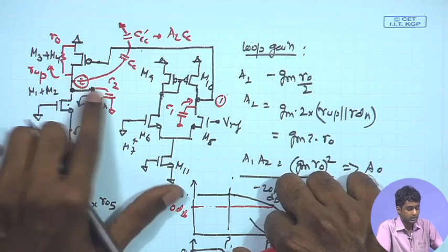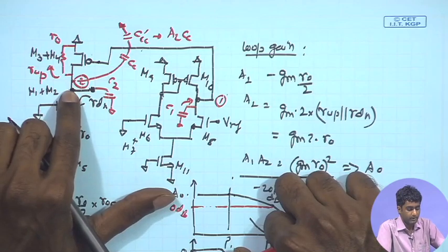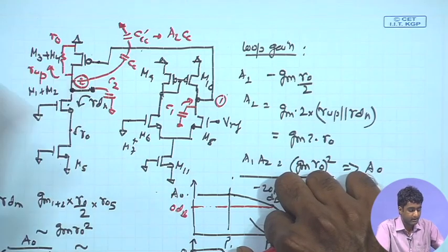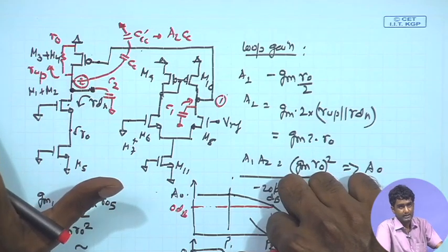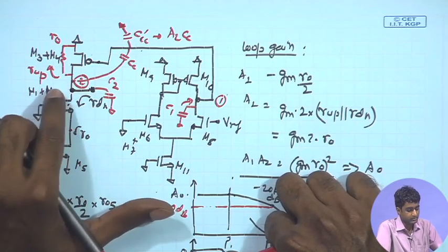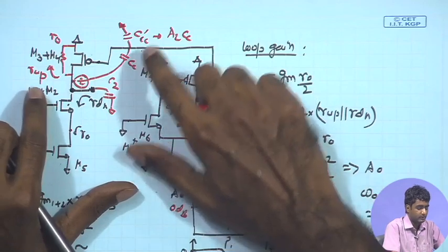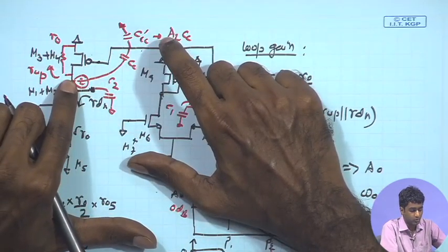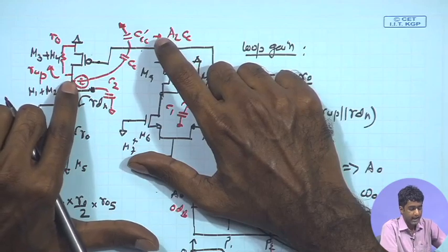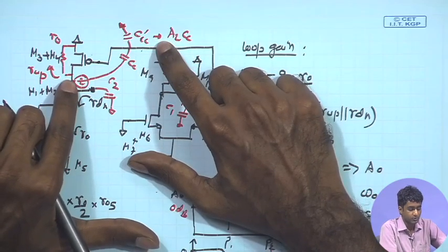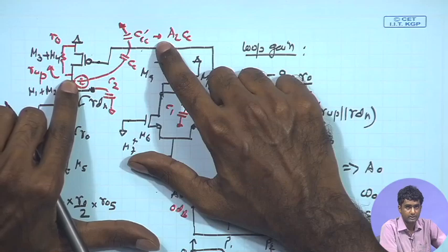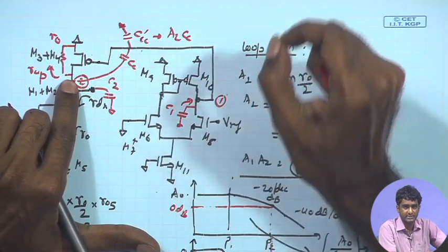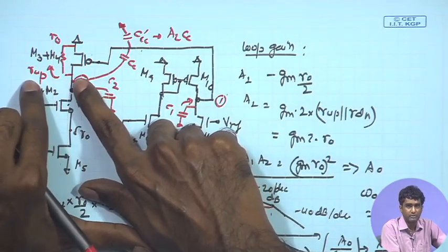So, you are still adding up a little bit of capacitance at this node as well, and that can interfere with your differential operation, because remember when we talk about the overall capacitance between this point and node 2 over here, in the actual differential circuit, this node is a differential node. It is not a single node tied together. We do not have a resistor with the help of which we are taking a central tap. This is part of the differential circuit.